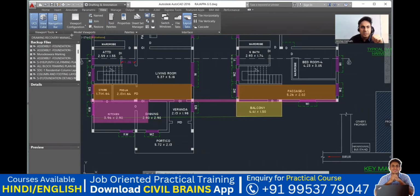Great. So this is 1.5 meter, and the length is 4.41 meter, because it's a balcony, right? You cannot take a big cantilever part. So you have to understand the structural concept. You could have taken a cantilever something like this also. But again, since it's a cantilever, if I have a beam here, this will be like a cantilever. So I have a beam here. This is your particular area.